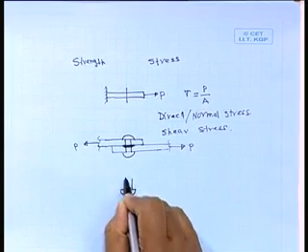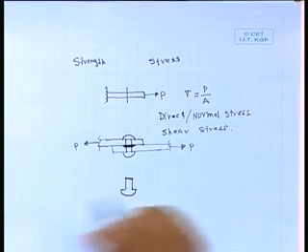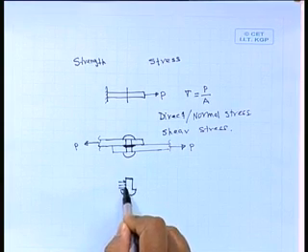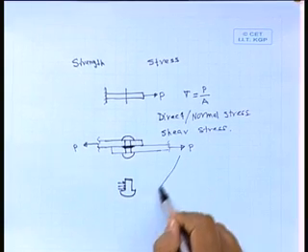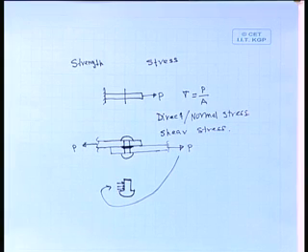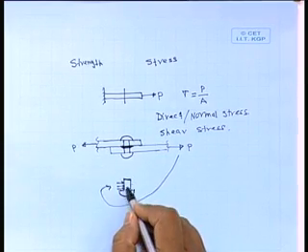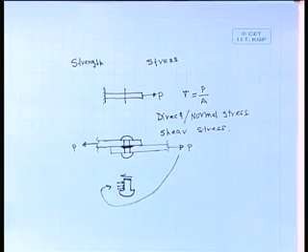So, that will be the rivet. If there is a failure of the rivet, it will be here, and the right side plate will apply some force on that, because whatever P will apply, that will be transmitted here in a distributed form, and it will try to pull to the right side, and the upper part will try to give a force in that direction, that will be distributed over the cross section of the rivet.